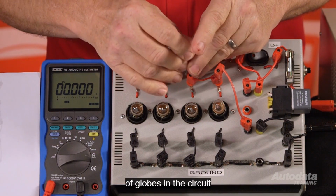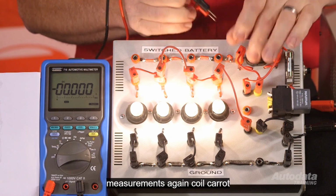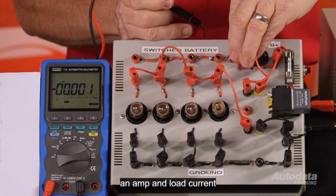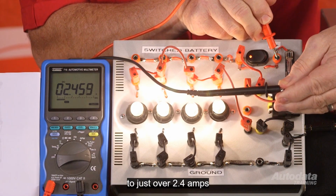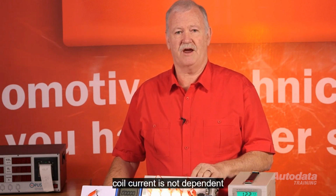I'll put another couple of globes in the circuit. I'll do the same measurements again. Coil current, pretty close to 0.14 of an amp. And load current, this time has gone up to just over 2.4 amps. A small current switching a much larger current. The small current, or the coil current, is not dependent on the load.